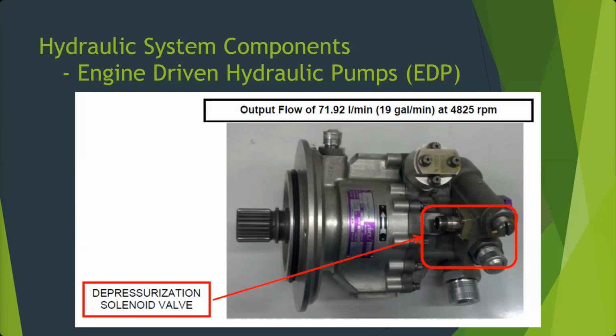You just have to be careful with that because it also in many cases cuts off flow to the case drain port. So there's a limit to how long you can run it that way, or it limits the flow of fluid through the case drain. And so the pump can only run for so long in that condition. It's used in an emergency function.